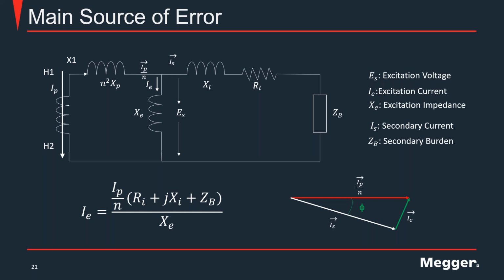In testing terms, we can magnetize the core either while running a saturation excitation test, or whenever we are testing with any DC quantity, either DC voltage or DC current, like when we measure winding resistance. We are practically aligning the atomic dipoles in the core of the CT.